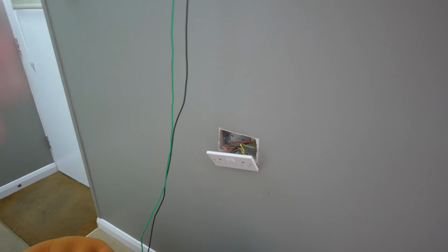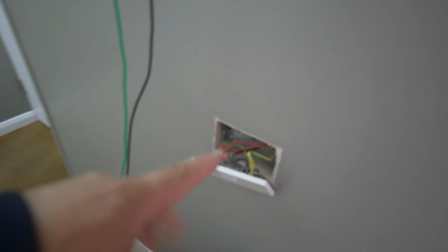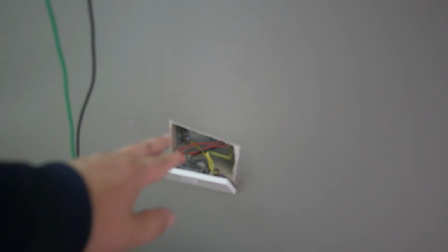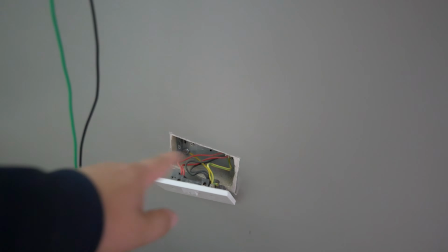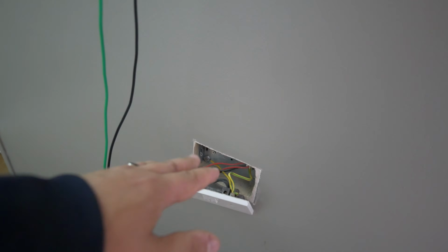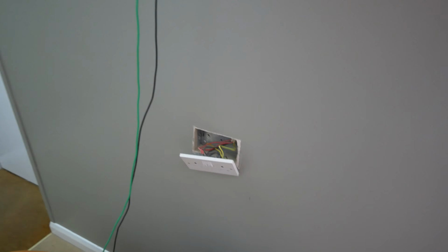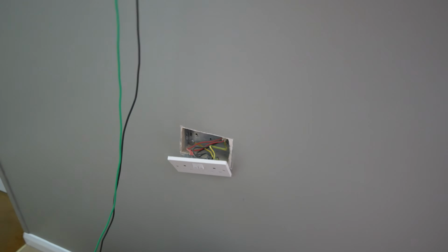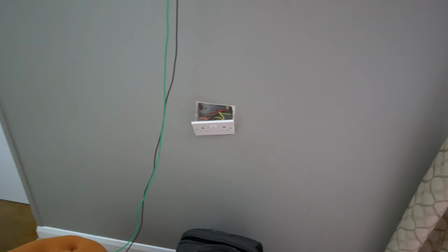Now obviously again, as I've shown on the channel before, if this was initial verification, you would do this anyway to verify your neutral conductor, but you'd make the same crossovers with the neutral and the line or the neutral and the CPC and get a value. I'm going to do that, just make sure we have got continuity around everything and that it pings out as normal. It's a good way of identifying any spares and see if there's any problem there. So I'm going to run around and do that, and then we'll move on to having a look at the R1, R2 on the lighting circuit.